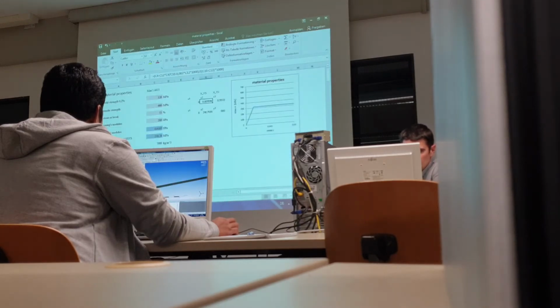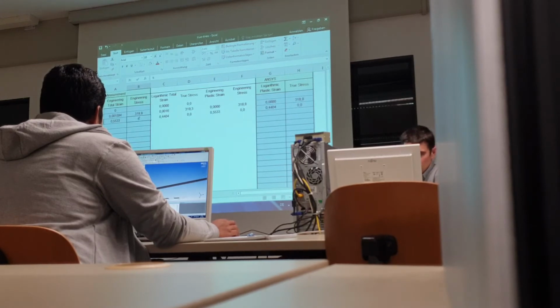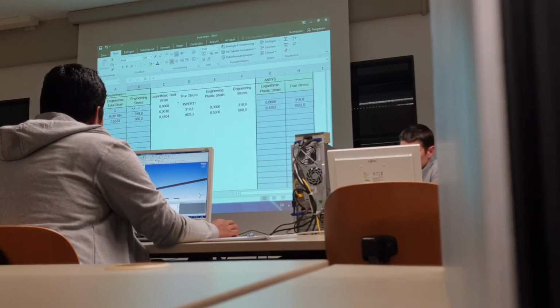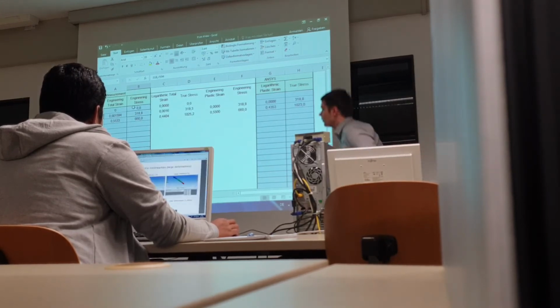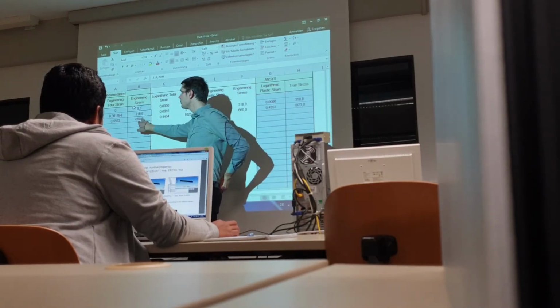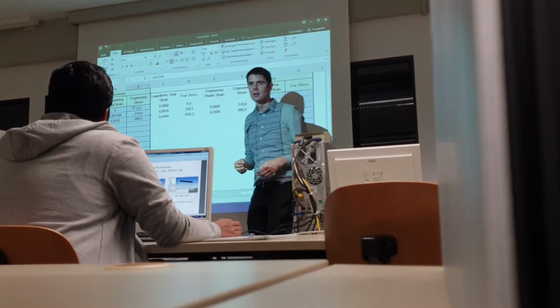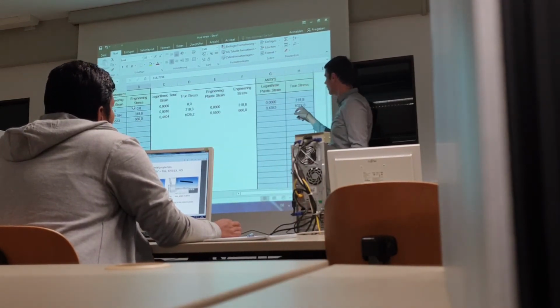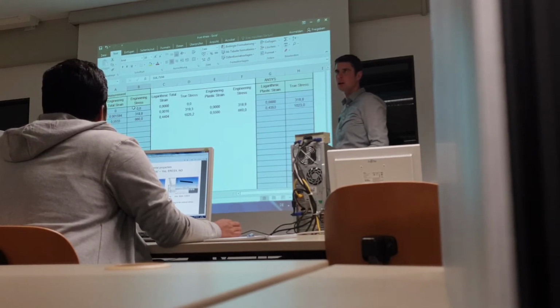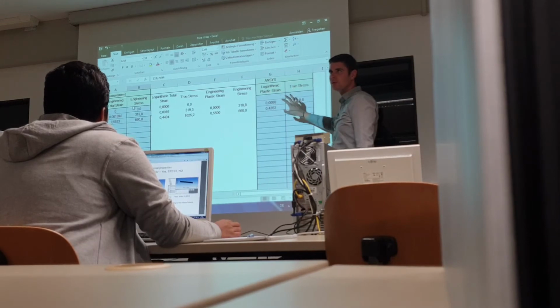And 660. These are the calculations, from engineering measurement to real stress. You see, stress at break by measurement was 660. Stress at break in reality is 1000. And ANSYS always uses this one. So what we define is this one.